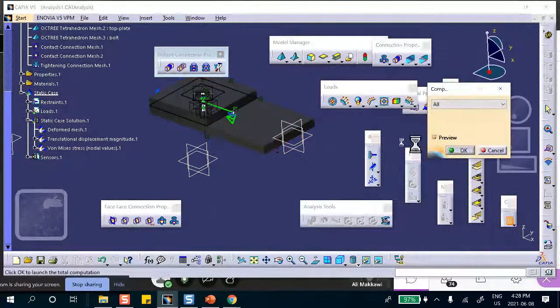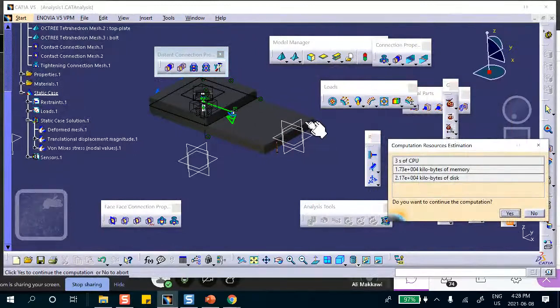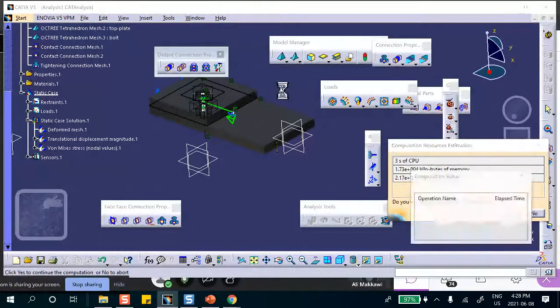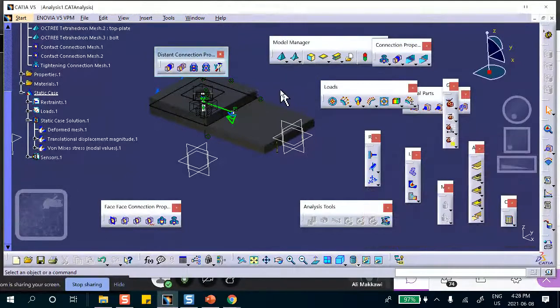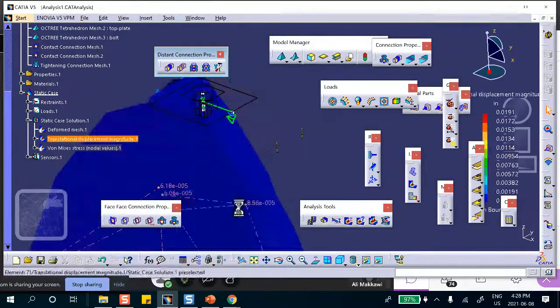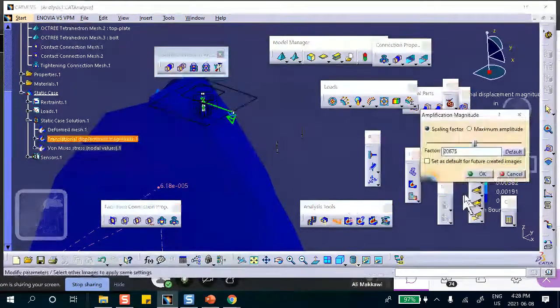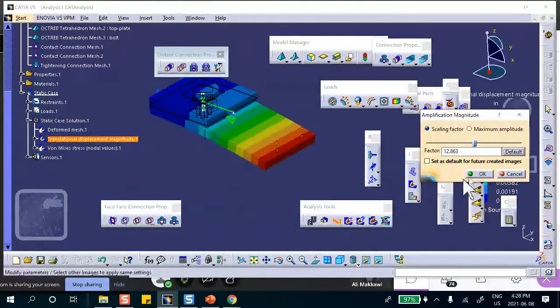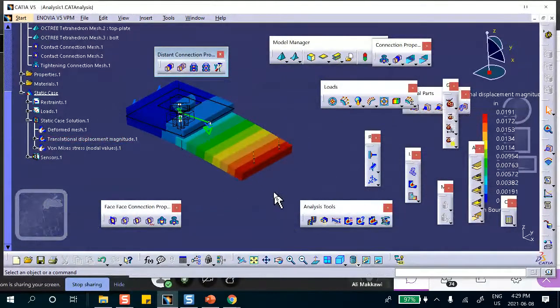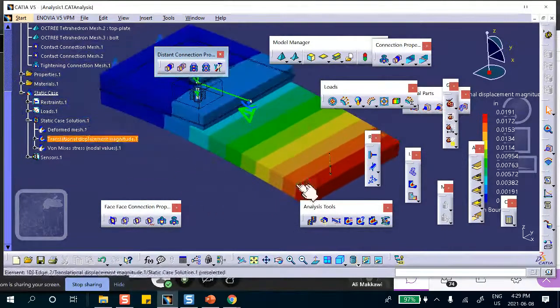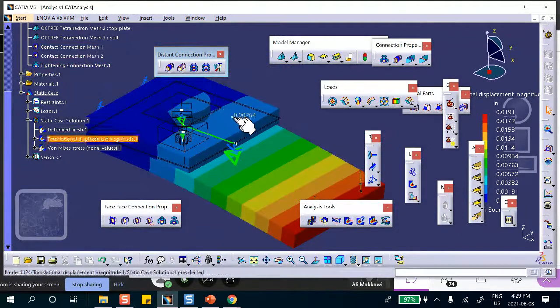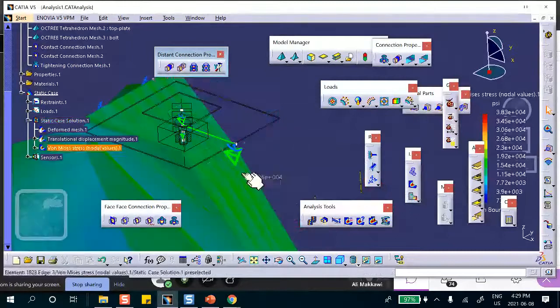You'll see that the bolt is going to be in action. It's going to put these two together, and of course this load is going to pull this thing down because these are clamped together. The top plate is also supposed to follow that. Okay, let's look at it. Let's look at the deformation first. Scale, scale, scale. There. Okay, good. So notice that this guy wants to go down. These are clamped together, and that's why this is also pushed down. Okay, and same thing with the stresses and things like that.